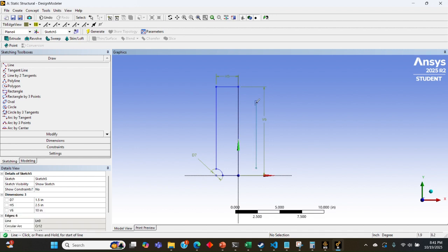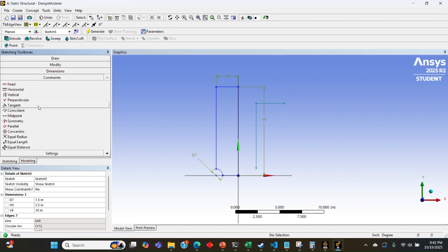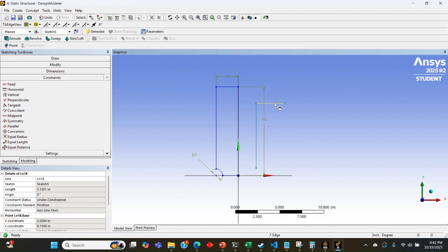And then if you make a horizontal line, you'll see the H show up. It will snap that line to another horizontal point. So rather than go in here to constraints and click perpendicular or parallel, it will make that line vertical or horizontal for you.